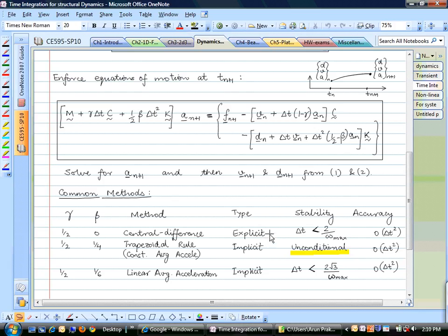Another benefit of using Abaqus explicit instead of Abaqus standard is that, let's say you have some structure and you apply some load, a static problem, not a dynamic problem. You apply some load and you will get some static solution. What Abaqus explicit will do is try to solve this problem in a dynamic way, but it will add damping to the thing.